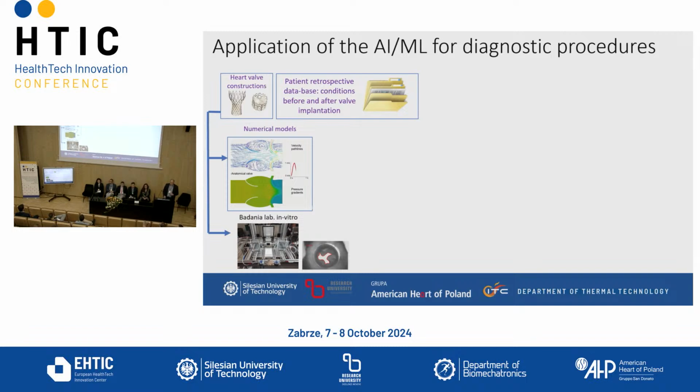So we can imagine that in order to develop the techniques that can be used for the treatment of patients, we need to have an appropriate range of data. We need retrospective data that can be combined with in vivo and in silico simulations. We are collecting retrospective patient data where we have all information about the implantation of the aortic valve. We have the numerical model, the CFD simulation, where we are able to simulate the flow through the valve and the interaction of the fluid, the blood, with the valve leaflets, and give a response about the possible interaction between them and possible kinetic energy generation, which can affect thrombus formation.